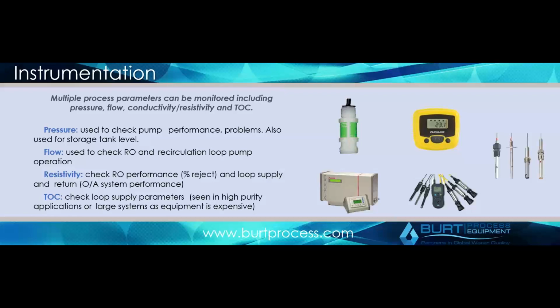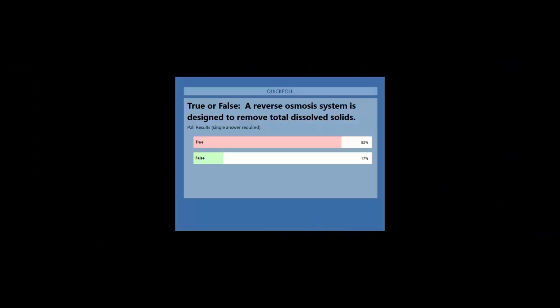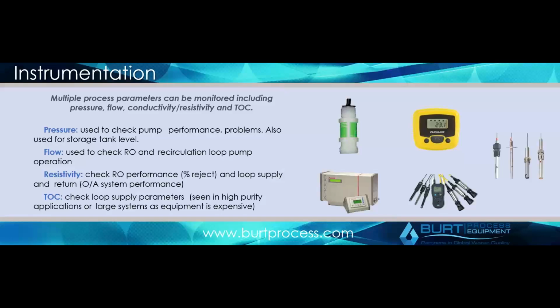And then you get into some of the higher end monitoring, such as TOC. TOC can be monitored real time by means of sampling within your actual system. And then you can move on from there to more elaborate ones, such as dissolved oxygen and silica sensors, when you get into the ultra high purity water realm. But your system will have a lot of these different instruments, which is why systems also tend to be PLC based controlled, because you are controlling a number of different processes which are working together.